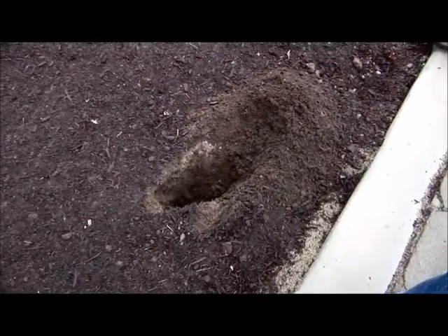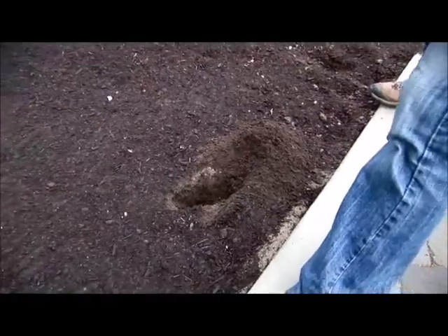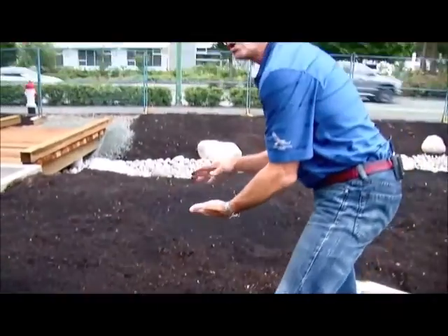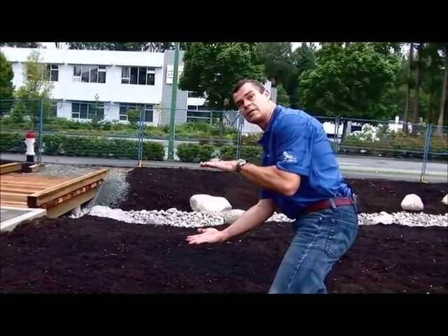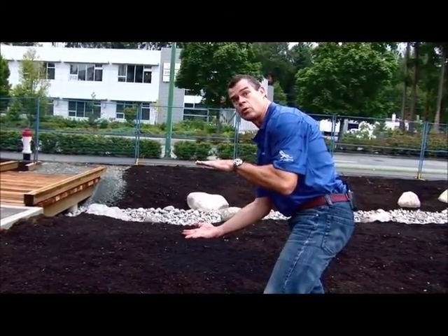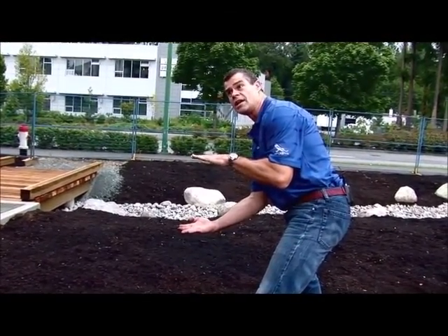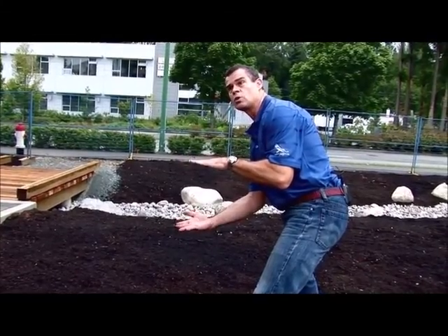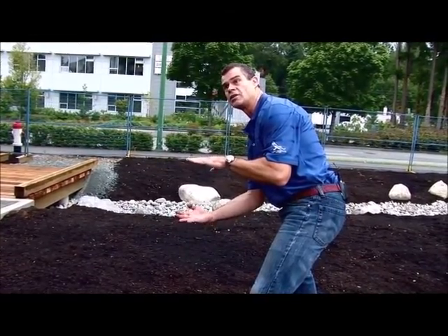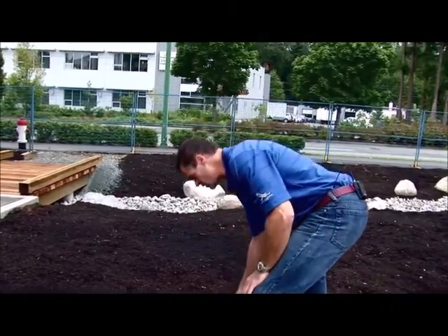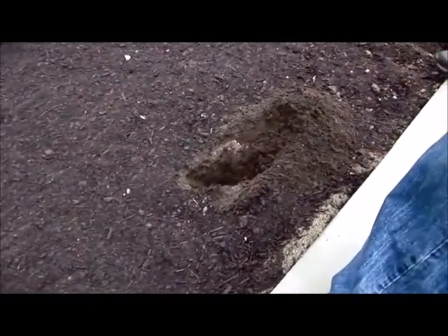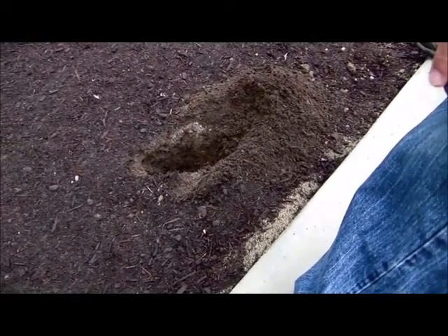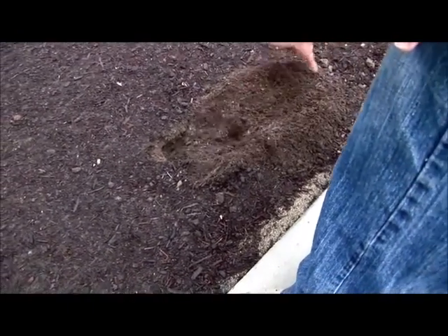One of the new standards we're working on is when they do landscaping here, we're really trying to encourage developers to use at least 300 millimeters of organic topsoil, because that's been found to be the most effective depth for soil to manage rainwater. So I've just dug a bit of a hole here, and they're using well above the 300 millimeter standard of topsoil in here, so that's great.